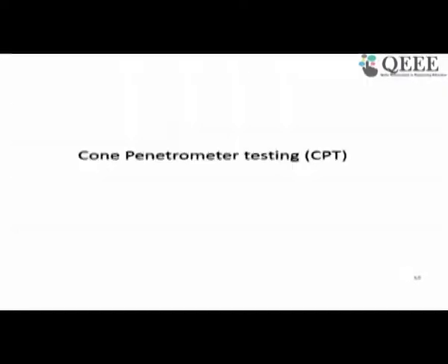Now we'll discuss the cone penetrometer testing or cone penetration testing. What we saw in the standard penetration test was very crude, where you have too many differences in strata, or different layers, or the strata is changing frequently.